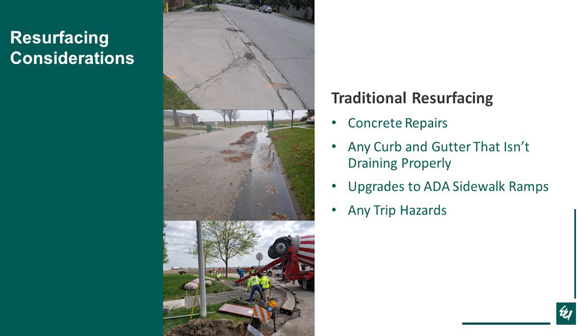And then everyone knows that you got to upgrade the ADA sidewalk ramps to the most up-to-date detail. Whether you want to add any trip hazards or any other sidewalk would be community dependent, but typically it's more cost effective to do it while you have a contractor there than do it in a separate program, but that would be community specific.